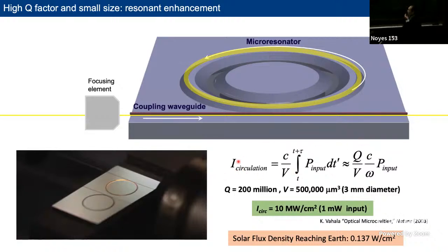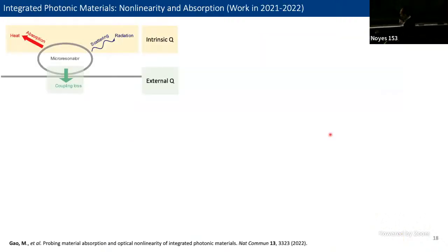Okay, so given the fact that Q factor is so important, I can see that from this equation, the intensity itself is proportional to the quality factor. And with a higher quality factor, you can get a higher intensity, which will be favorable for the applications in nonlinear photonics. And also, other nonlinear optic processes probably involve multiple photons that are interacting with each other. In those cases, some critical parameters may even be proportional to the square or cubic of the resonator Q factor. So Q factor is really an important factor that we care about in the applications of high quality resonators.